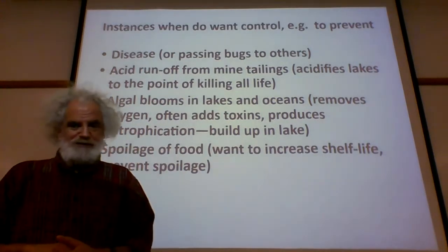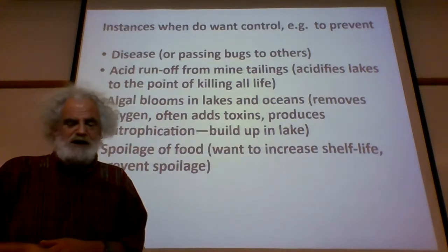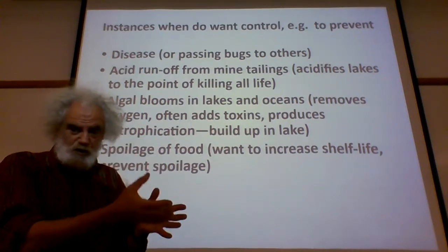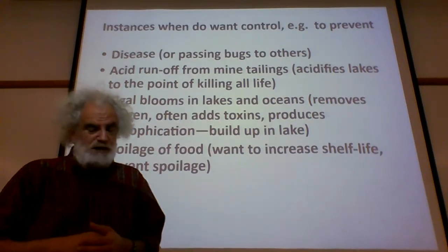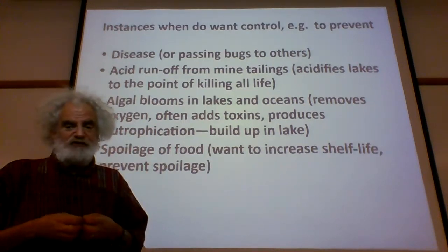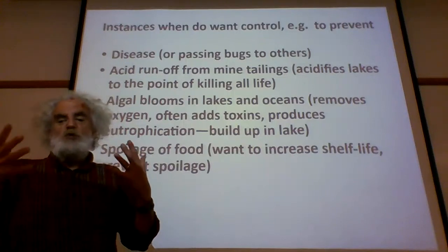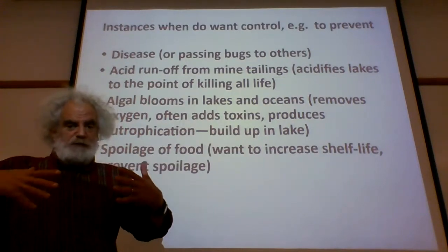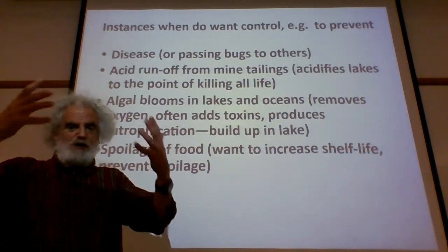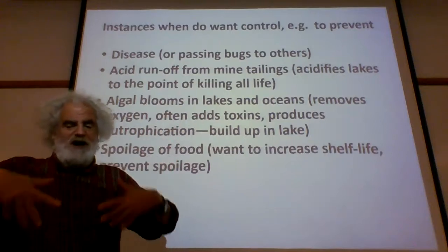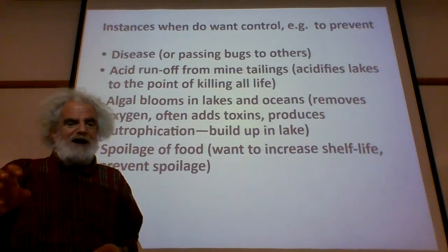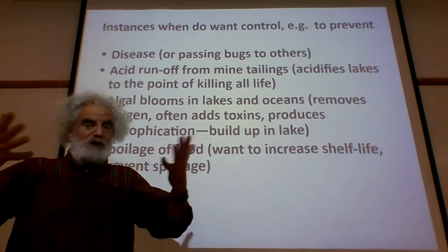And so if you go to a sewage treatment plant, that's one of the things they're checking every day: the level of organic material in the water, the effluent, and the ability of bacteria to chew on that and suck the oxygen out of the water is a bad thing. So what you want to do is have the sewage treatment in the plant work so lots of bacteria are growing on it and eating it all up, and lots of oxygen is being introduced into it. So then when you dump it out into the Sangamon River, you don't have this biochemical oxygen demand anymore. It's already been consumed.